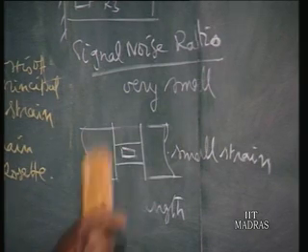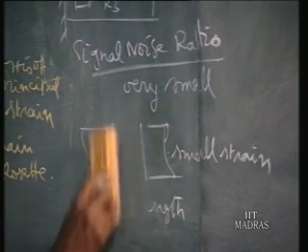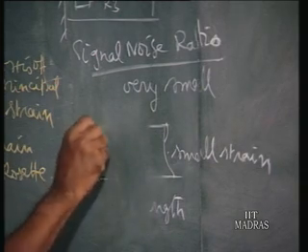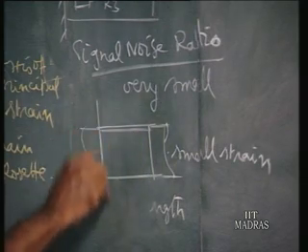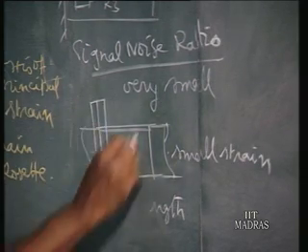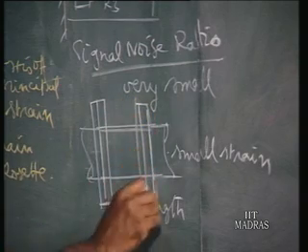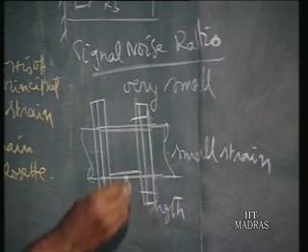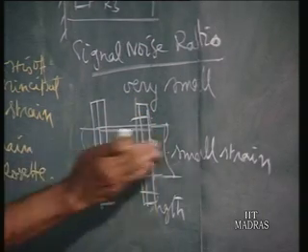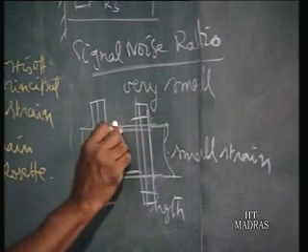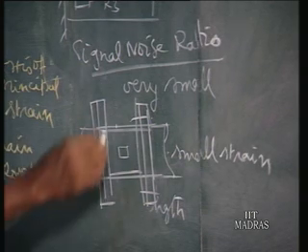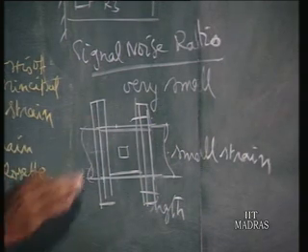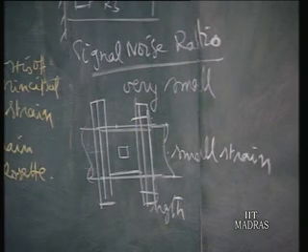For that purpose, what is done is, instead of a solid piece you go for a tubular construction. So from here to here you have the tubular construction, and you fix it with a flange, with a bolt, and the middle portion alone is tubular; the other portions outside are solid pieces. Now you can paste your strain gauge, one here, one at the other side, and so 2 or 4 means Poisson's configuration you have to fix. So you have to ensure sufficient signal to noise ratio. That is possible only if you weaken the surface.